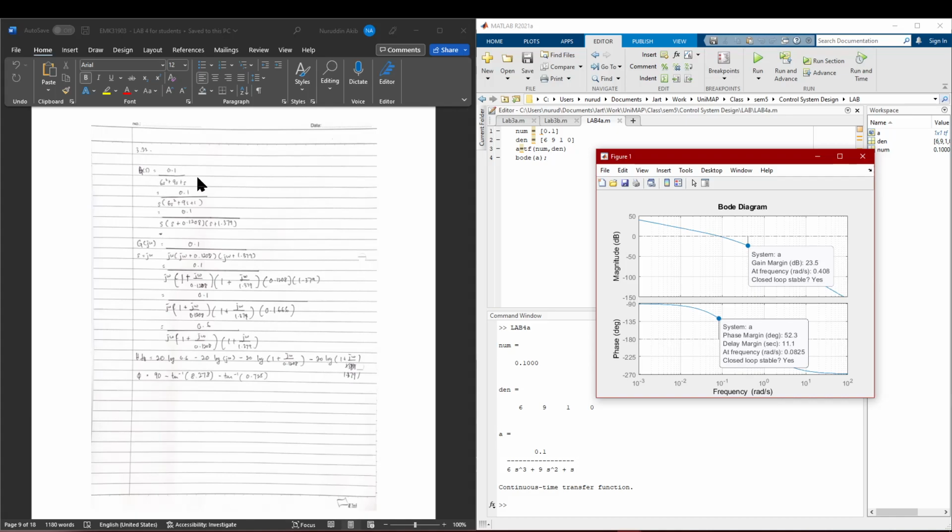We take the equation from before, and then we factorize it to get the bracket one, and then we replace s equal to j omega. So all the s will be j omega, and for the plotting it is compulsory to get the plus 1 here.